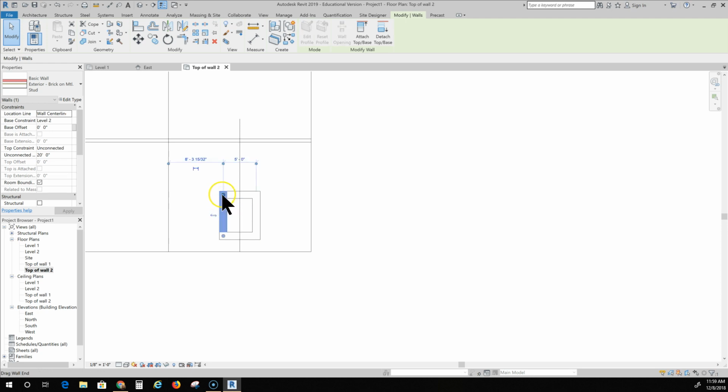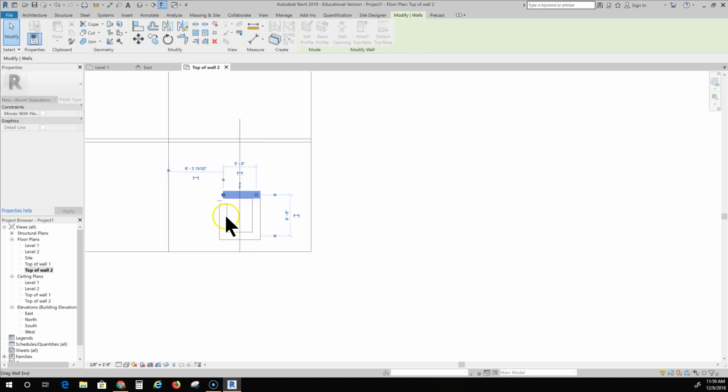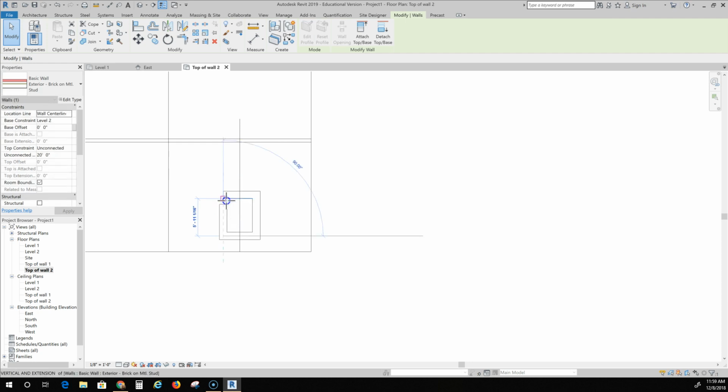So I'm going to take this wall, pull it back a little bit. I'm going to take this wall, pull it over a little bit so it kind of understands that I want that to be the main wall in the back. So now, as you can see, that wall extends all the way from one side to the other, and that just makes for easier modeling later on. And of course, my front wall is already that way, so I'm going to keep it just like it is.